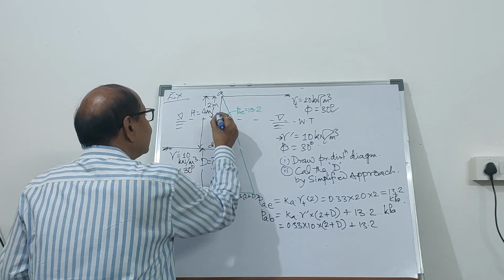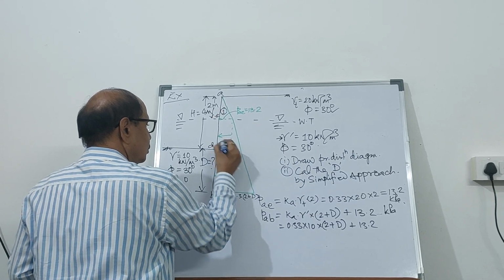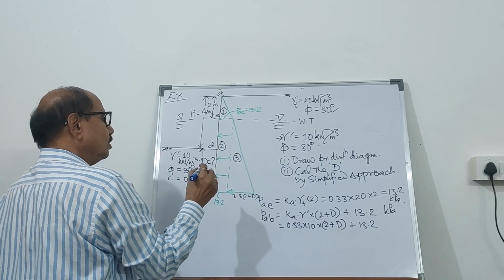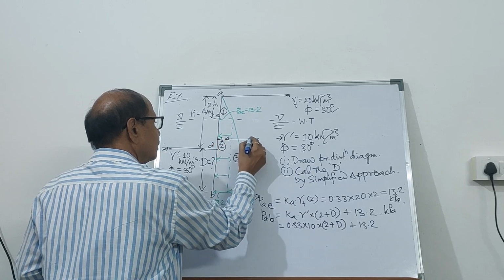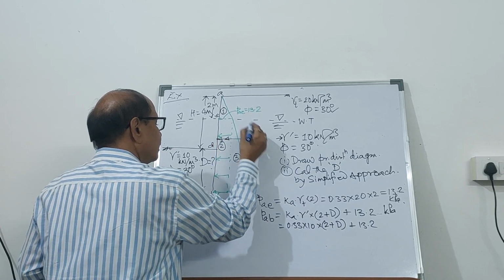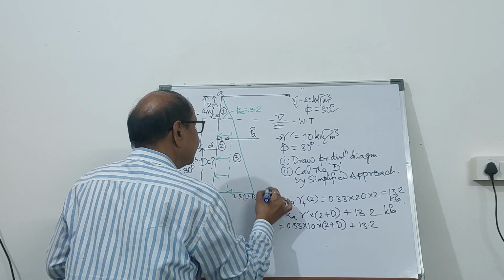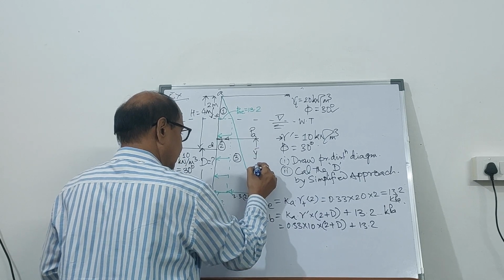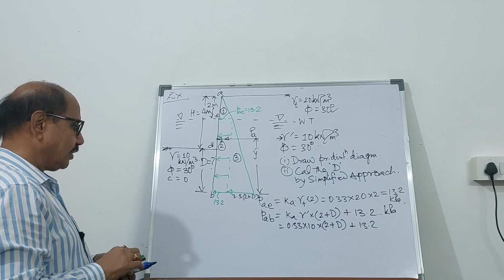So you have got on the active earth pressure 1, 2, 3. So what is the line of action of the active thrust? Calculate this PA and also its line of action from the bottommost point, so YA bar from the bottommost point.